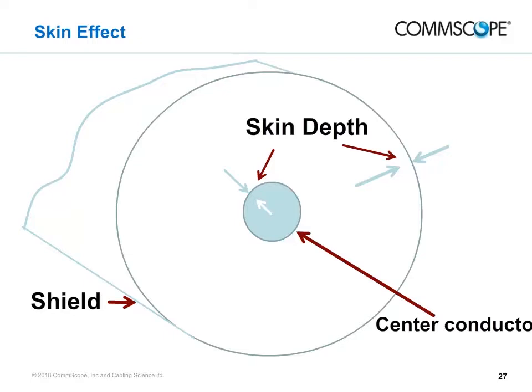at different frequencies. Skin effect causes the conductor to behave electrically as though it were a tube of material whose thickness is equal to the skin depth, with the current distributed equally throughout its volume. Since skin depth decreases with the square root of frequency, so does the effective size of the conductor. This phenomenon contributes to cable system frequency response that was discussed earlier.